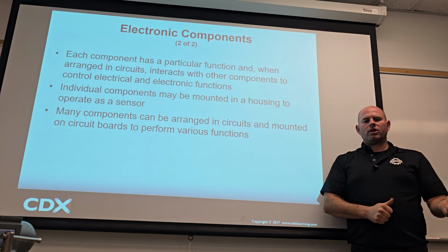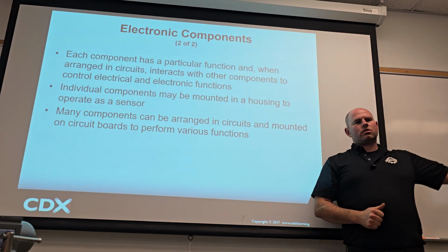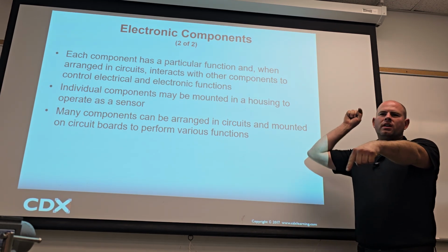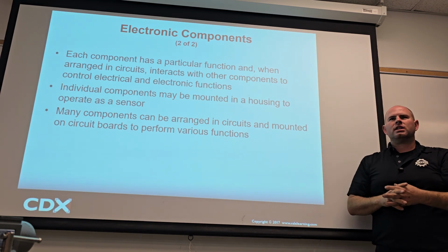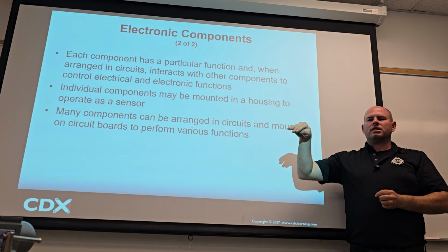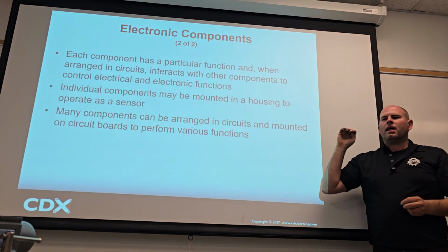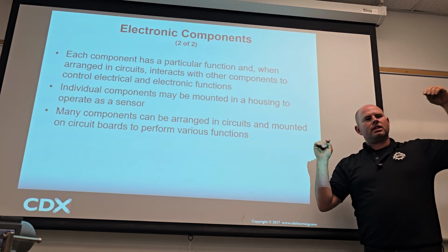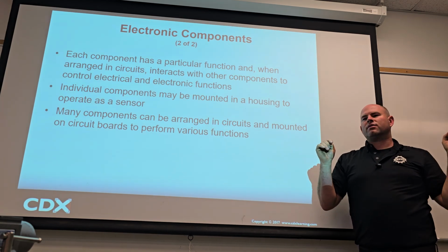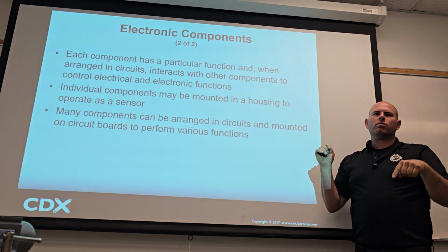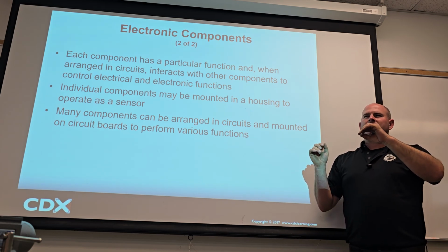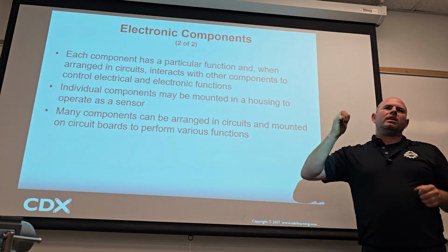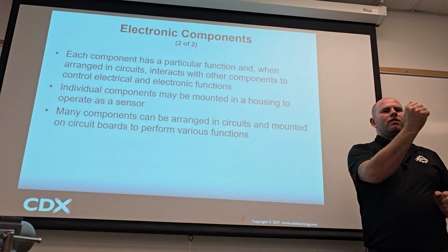The way the heater works is pretty simple. We give it 12 volts on one wire. We give it ground on another wire. The ground wire is usually, let's just say in this case, we'll simplify it, grounded all the time. The heater wire, we have to actually give 12 volts or not give 12 volts. The way that the computer will do that is it'll use a transistor.